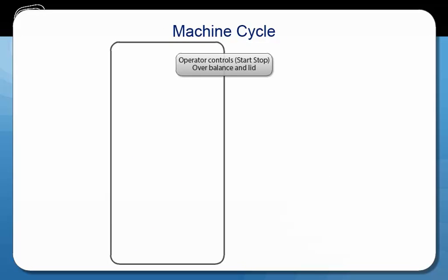In the main program, we have the start-stop controls plus the calls to the subroutines. When the start button is pressed, the variable cycle is turned on. It will stay on until the machine completes or the stop button is pushed. The fill subroutine is called. We want to run the subroutine until the machine is full, and then we don't want the fill to have an effect until the machine is restarted.